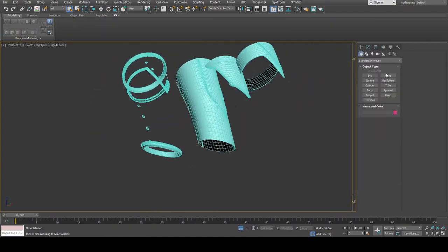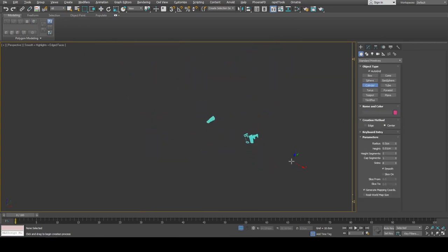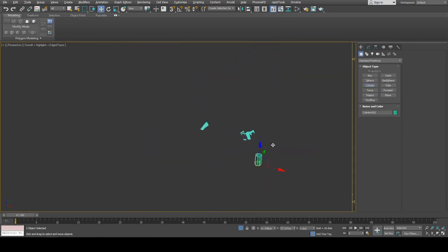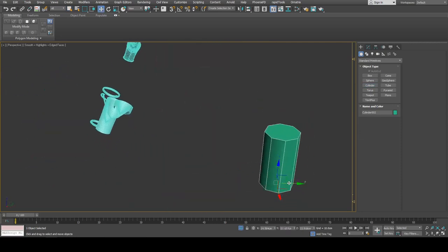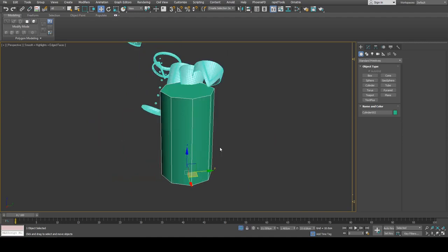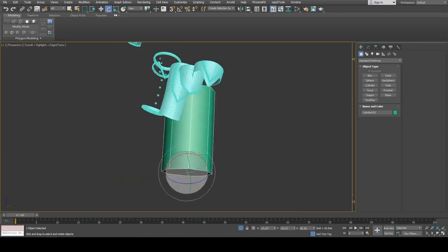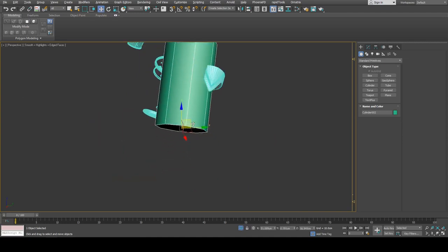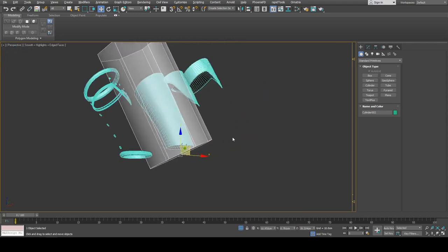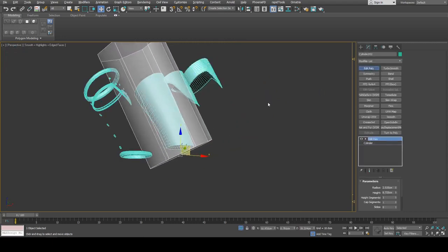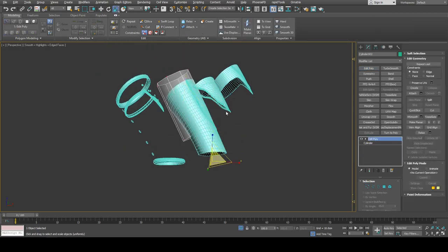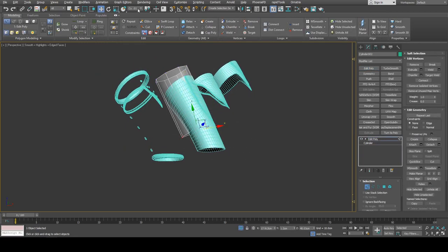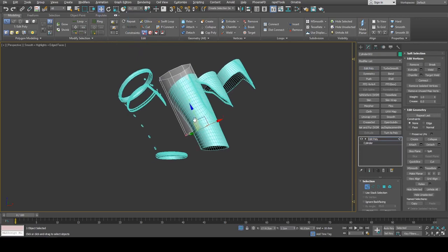So in order to model something like that, I can just create a cylinder. And so what I can do when you're modeling here is you want to keep it without reset X form for as long as you can. You can only reset X form once you're done. And that'll just make it easy to apply symmetry. I'll choose pick the object itself.